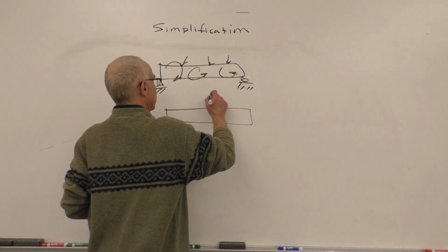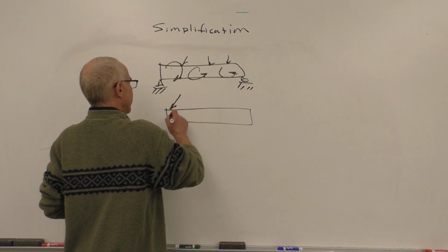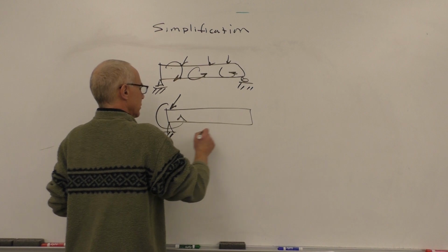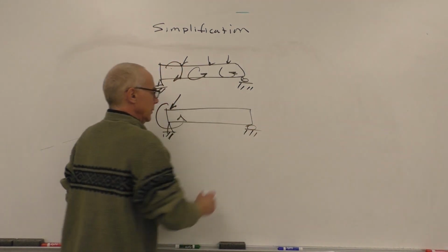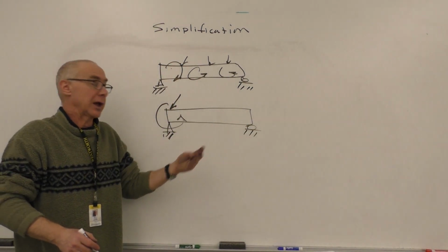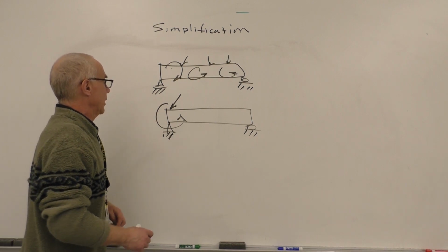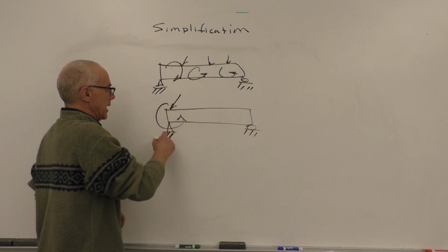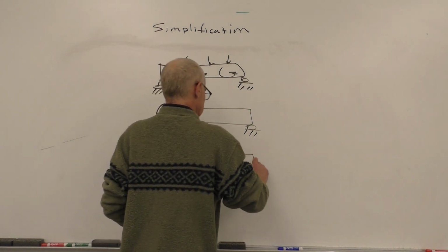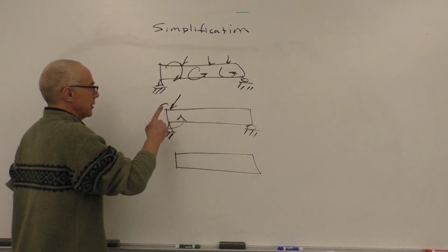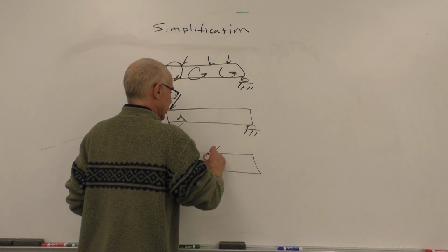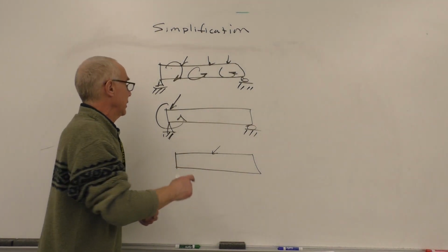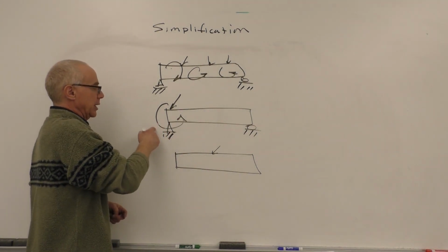We're going to reduce that to one vector and one moment. And that's what we did last time, and we actually went through an example and showed that. But we can actually do one better, which is we can take this moment-force combination and simplify it to one force, but applied strategically so that the force times the distance equals that moment at that location.